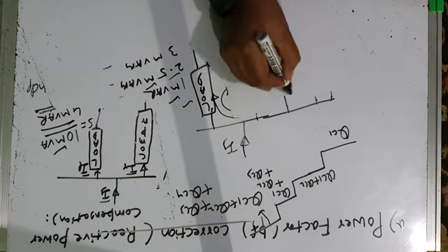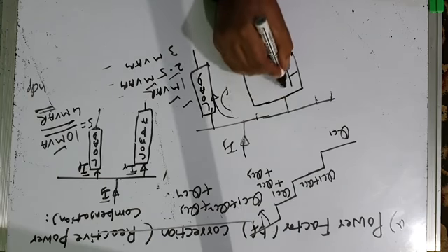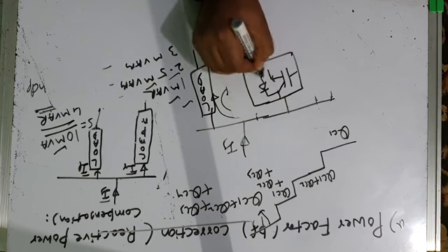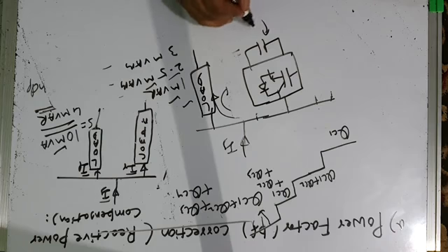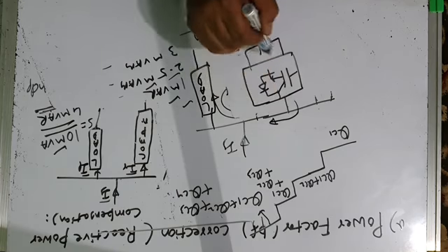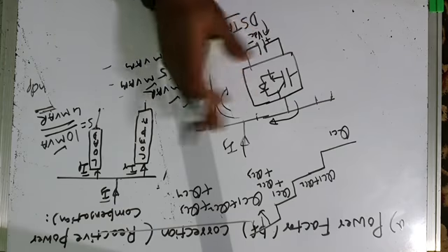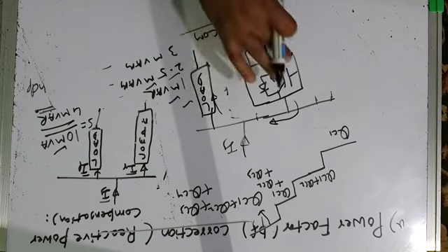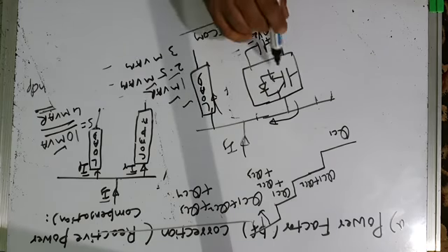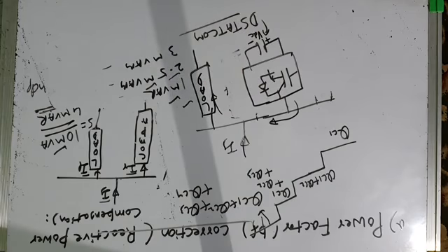Okay, the modern power electronics based compensators are not capacitor compensators. In modern power electronics we connect D-STATCOM. You'll study that in future lectures. The voltage source inverter like this, it is called D-STATCOM, distribution static synchronous compensator, which is a voltage source converter having a DC link with VDC voltage, which converts this DC voltage into AC voltage, and it provides continuous and smooth reactive power control, continuous and very fast response. The load reactive power demand may vary quickly, and this caters to that. The response of this is very fast, and it smoothly and continuously controls the reactive power. It gives a better dynamic control of the load compensation.